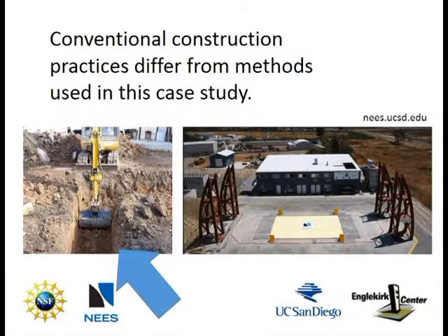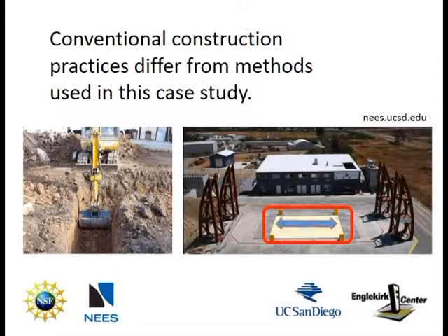This table, found at UCSD, is an outdoor shake table with a one-direction axial loading feature. Missing in this video is the initial step of excavating the earth in order to place the foundation into the ground. When constructing a specimen on a shake table, the test structure is cast directly only to the top of the steel platen, requiring formwork to support the sidewalls of the foundation. In the field, however, shallow footings can make use of the natural sidewalls provided via the excavated earth. But formwork in the field is required if the sidewall of the foundation extends above the natural grade or ground level.